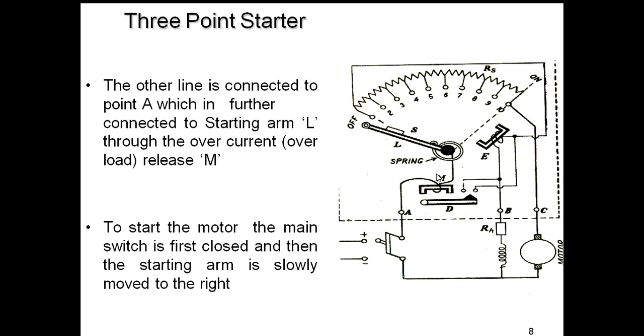To start the motor, the main switch is first closed and then the starting arm is slowly moved to the right.